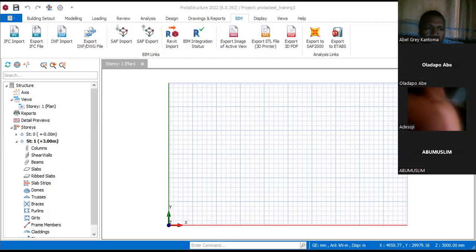So where I'm going to be placing the edge of this particular steel here is going to be a grid. Here is another grid. Here is another grid. That's an axis. Here is also going to be an axis. So I'm going to be having 1, 2, 3, 4. Now, from here to here, the width is 5 meters. From here to here, the width is also 5 meters. Then from here to here, I'm going to make it 3 meters, but this is more than 3 meters what is here. Okay, but in this modeling right now, I'm going to make it 3 meters.